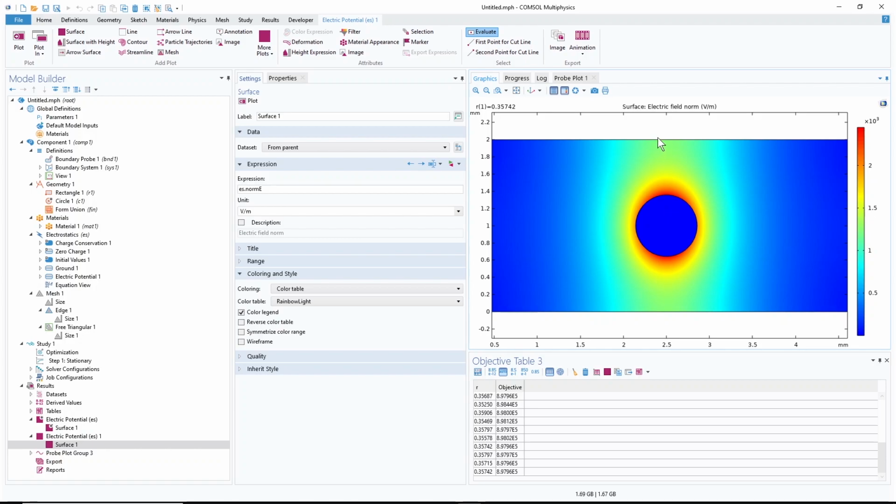So both boundaries, if r is very small or r is very big, the value of electric field will be very large. So then there is a minimum in between, and that minimum is whatever the solver finds right now. It's at 0.35, and that minimum is around 2400 volt per meter. So we will never be able to get 1500, but actually this value that it gives is the closest one to the one that we asked for.